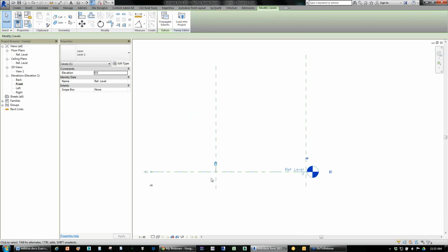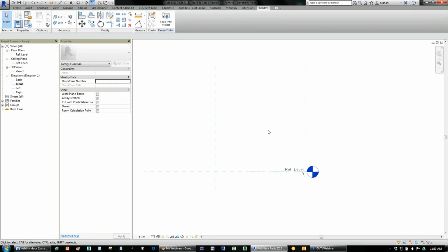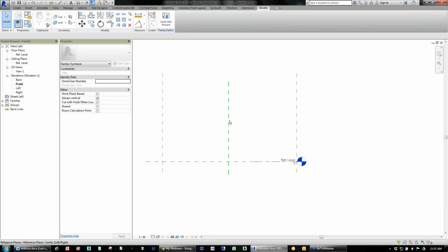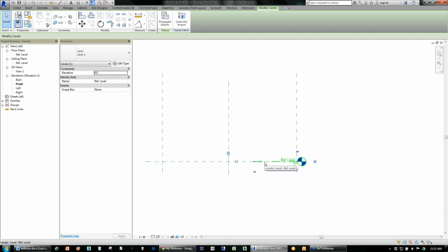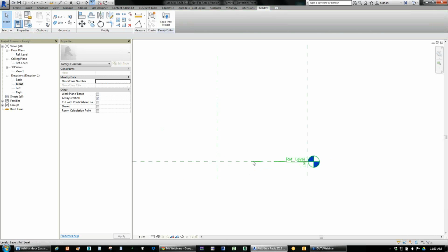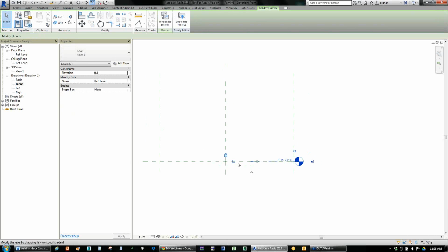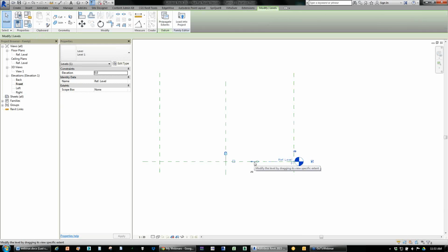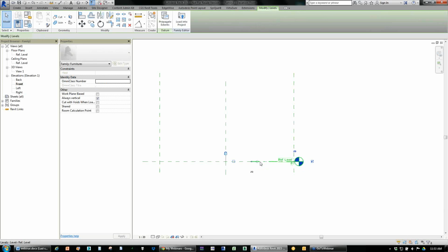What I've also got here is this reference level. Now that's a little bit different. I'll just drag that over away like so. What I've got at the bottom is a reference plane, just like I had here, and then I've got this reference level object. When we are placing dimensions, we always dimension to the reference planes. That's that same analogy of the muscles and the skeleton being correctly connected. You don't want to be dimensioning to this reference level. That can be a problem.